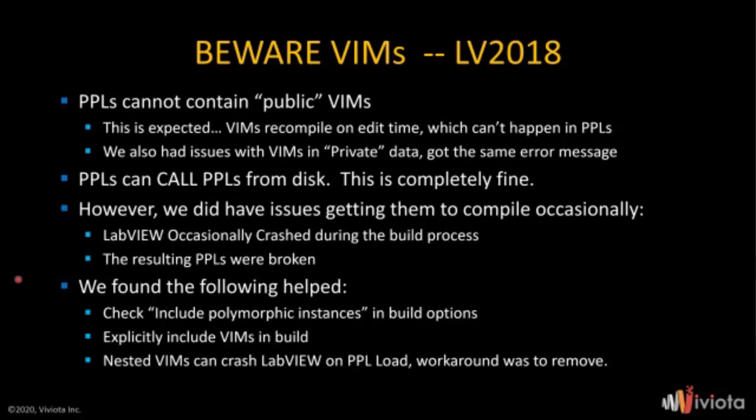The things that we found that helped are include polymorphic instances in the build options, explicitly include the VIM itself, and avoid nested VIMs. That was one we couldn't get around. Nested VIMs just ended up in crashes.